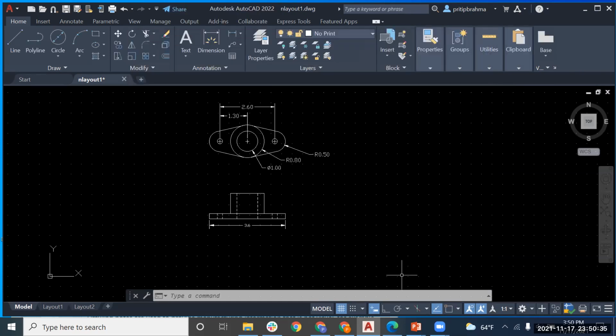And it would be letter, not ANSI A? Or does it not matter? Actually, they're the same. It just depends on what your preference is, right? I don't know what you're working in. Are you working in inches or millimeters? I personally am working in inches. I don't know if other people are working in metric. So if you're working in inches, just go with your inches format. If you're working in metric, go with the metric paper layout format. It's all the same, right? They're just different naming conventions, but it's for the same size.